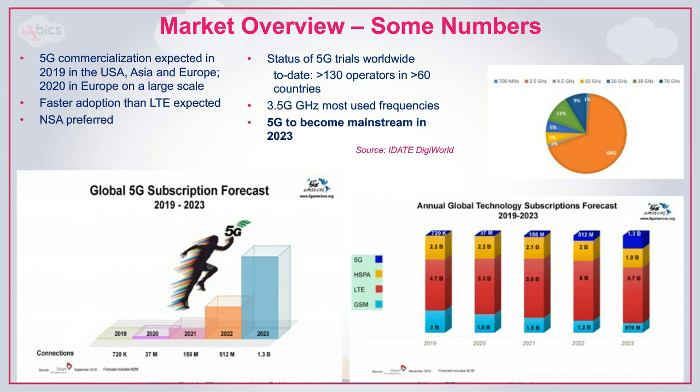Today, the main focus is the 3.5 gigahertz band, but we also see many operators working in the 26, 28, or even some allowance in 70 gigahertz. Of course, the higher you go, the more antennas, the more base stations you need, which makes it also a very expensive network to deploy on a nationwide scale. That is why today you see that many operators focus mainly on the big cities. And of course, then you need the 4G compatibility to go with it.